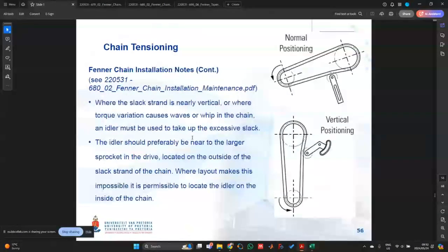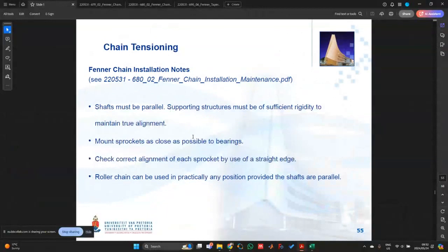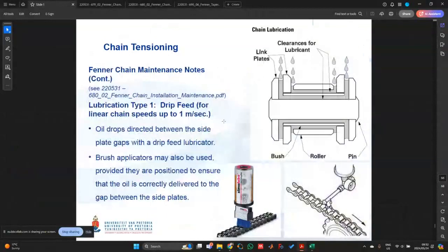We said that an even number or an uneven number of drive sprocket teeth should engage with an even number of driven sprocket teeth. I think that was the mistake that I made over there. It's actually, if you have an odd number of driver sprocket teeth, then you rather want an even number of pitches on your chain. I think that's the correct statement over there.